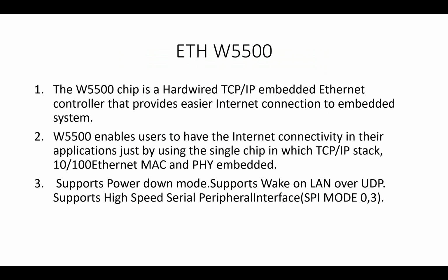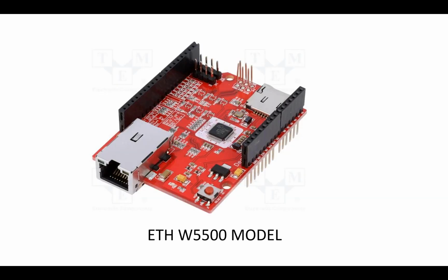The W5500 chip is a hardwired TCP/IP embedded Ethernet controller that provides easier internet connection to embedded systems. W5500 enables users to have internet connectivity in their application just by using a single chip with the TCP/IP stack. 10/100 Ethernet MAC and PHY embedded systems are connected through it. So it supports power down mode, supports wake on LAN over UDP, and supports high speed serial peripheral interfaces also.